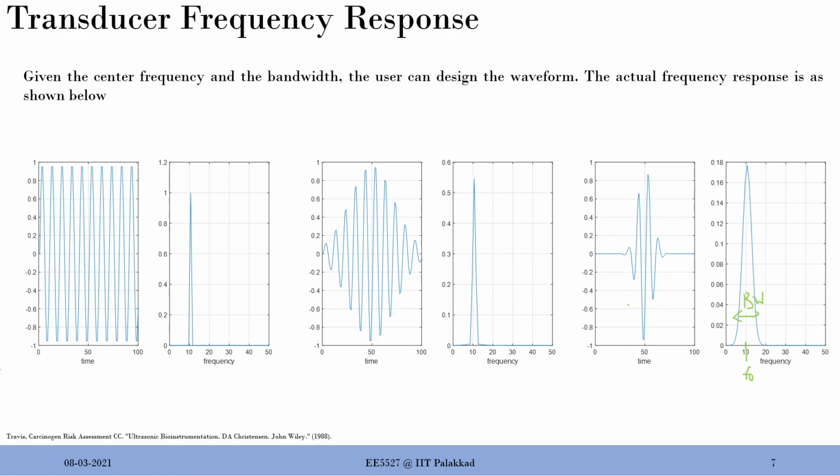You realize that in the last slide, because the size actually determines the frequency. The frequency actually determines the wavelength. And the wavelength, or the frequency, has an importance which we will discuss when we talk about the resolution and all those aspects. But it's important to see that the waveform is not infinitely long. We will damp it, and the moment you damp it, you will not have a single tone. Instead, you will have a bandwidth around a center frequency. So that is very important.